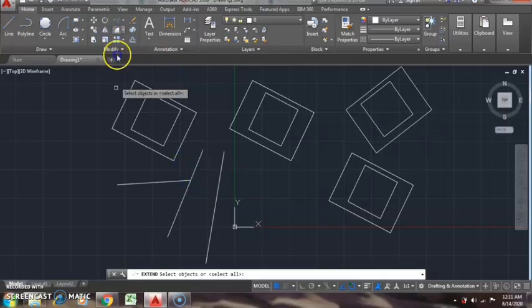And I just selected the extend command, and we can use as such the trim command with boundary or without boundary. With boundary we get the line extension up to that boundary. Without using the boundary we get the line extension up to the adjacent boundaries.